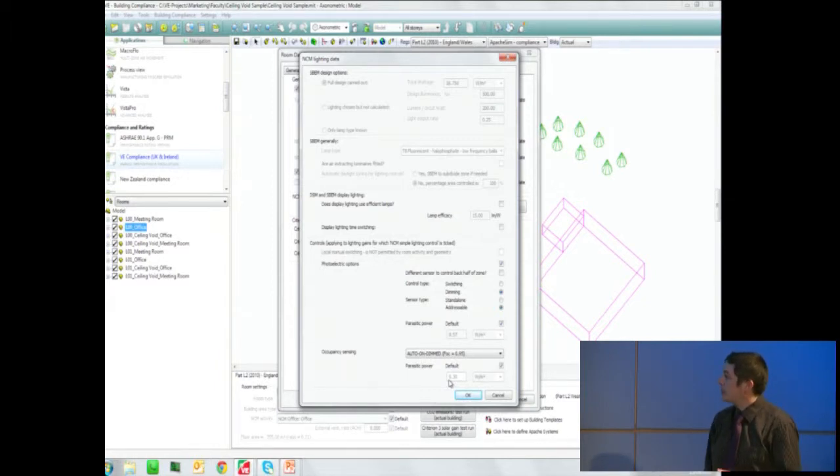to have applied. Now, in my experience from looking at other people's models who've looked into the true values of parasitic power, I find that this is significantly greater than what they would find in design. And while it's a relatively small figure on its own, this is going to have parasitic power that's run 24 hours a day, 7 days a week. It does build up. In a model I looked at recently, it accounted for something like 3 kilograms of CO2 of the building's BER.